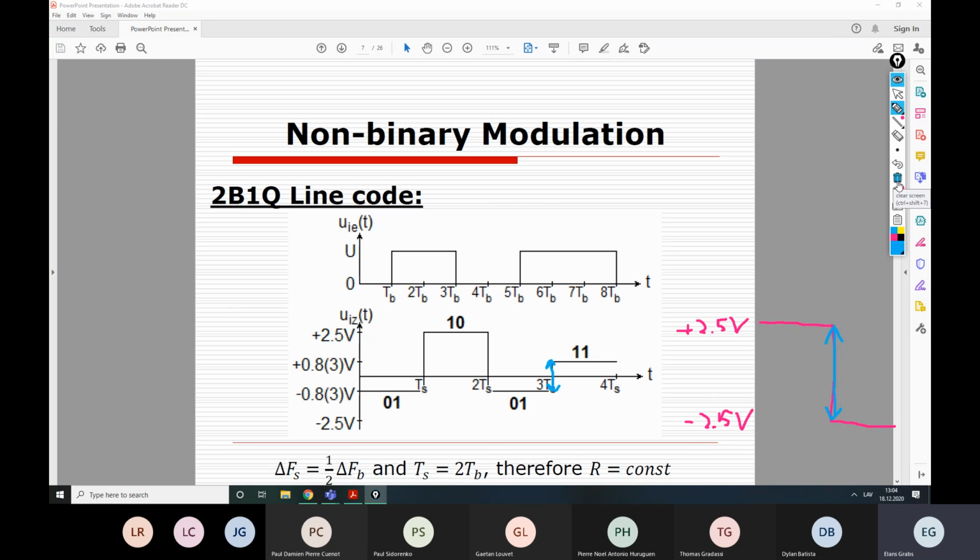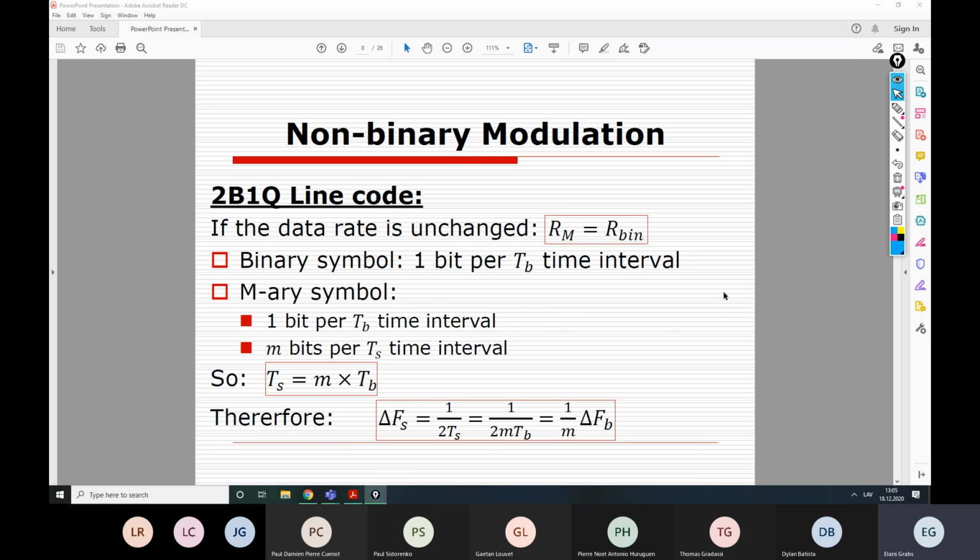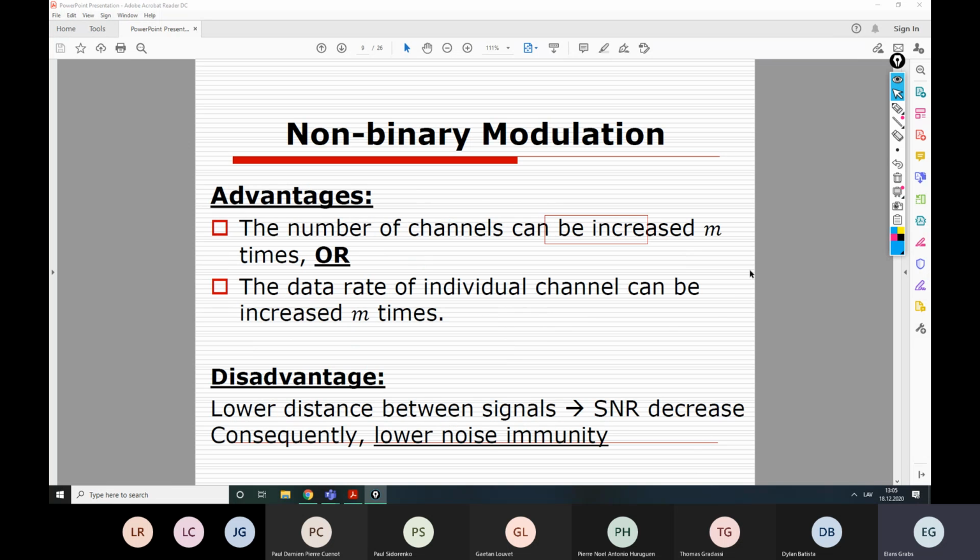So we only use these methods when we are sure that we are sending, for example, over a short distance, or maybe we have optical fiber with less interference and so on. So we need to be aware of the noise situation, because noise immunity is lower, and the more different levels we take, the worse the situation becomes, right? So here we have to be very careful.